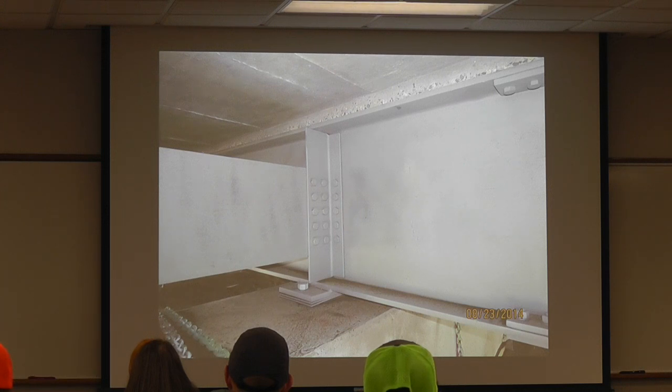I'll go with, I don't know, mill scale. Okay, so when steel comes from the foundry, in the cooling process, it forms a thin outer layer, is kind of the rough way of putting it. So when you go to blast that steel, you have to try and get as much of that mill scale off there as well and get back down to the raw steel beneath.